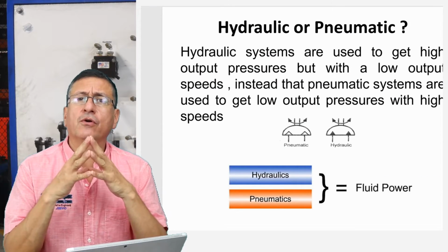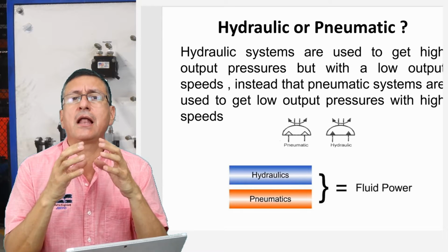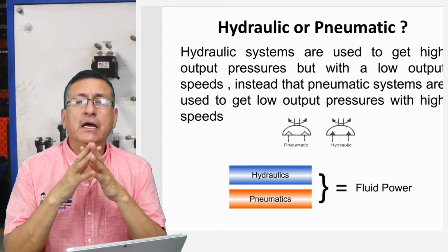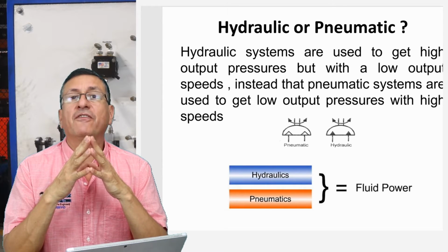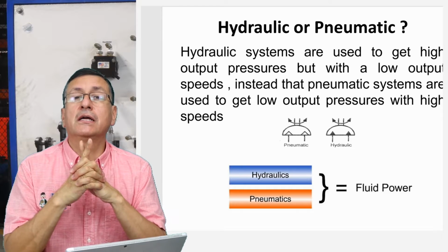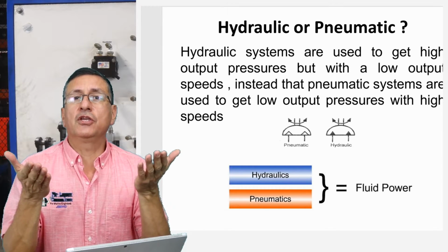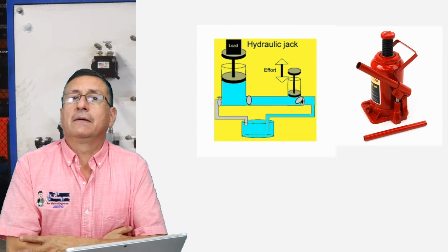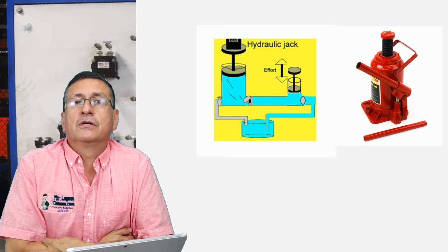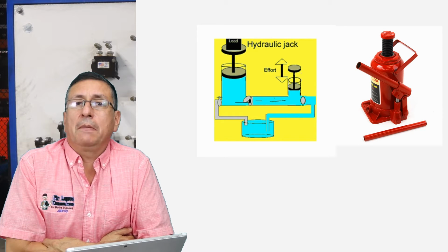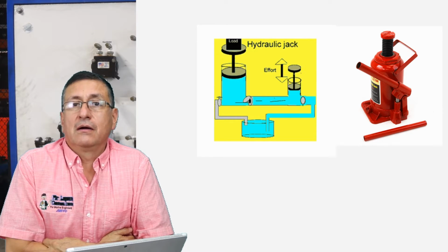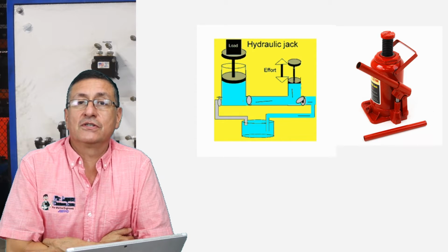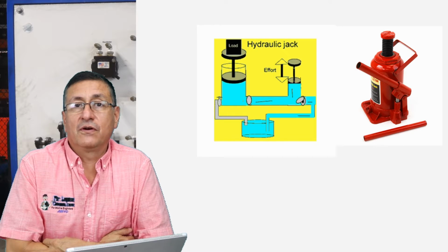Okay, my friends, right now we are going to start to study in details the Pascal law. To study the Pascal law, normally I use a perfect example that is the hydraulic jack. It's the jack that you have in your car, the bottle that you have in the hydraulic jack. This is a perfect example because with your hands you apply a small force. However, you lift your car of 3 tons, 5 tons, depending of the bottle.